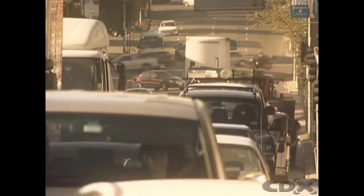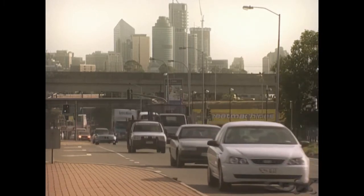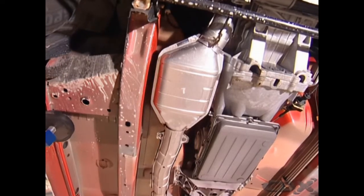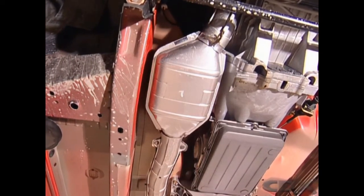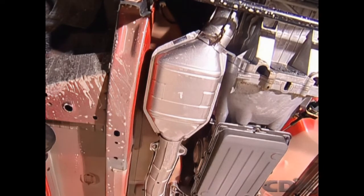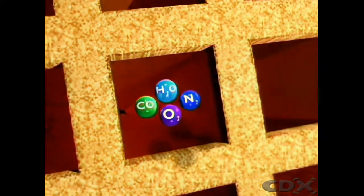A catalytic converter is used to convert unacceptable exhaust pollutants, such as carbon monoxide, certain hydrocarbons and oxides of nitrogen, into less dangerous substances. The catalyst inside the converter starts and then maintains a chemical reaction in the exhaust gases. A catalyst is a substance which causes a chemical reaction to occur, but is not affected by the reaction and remains unchanged itself.